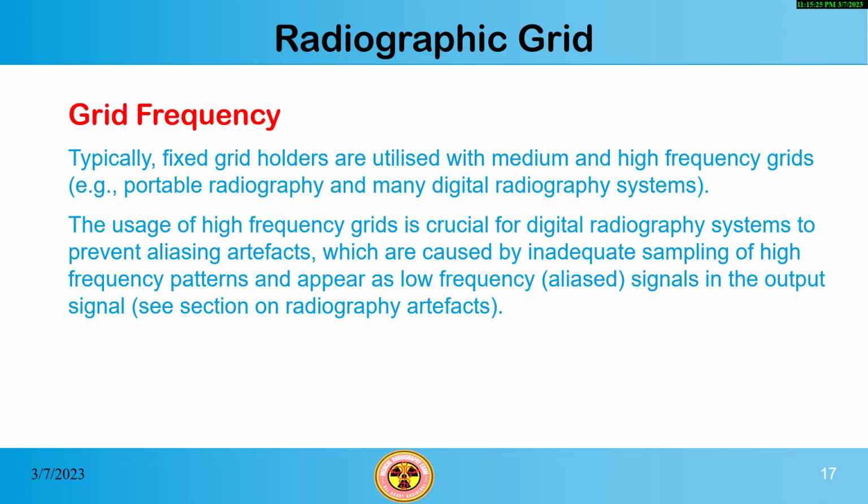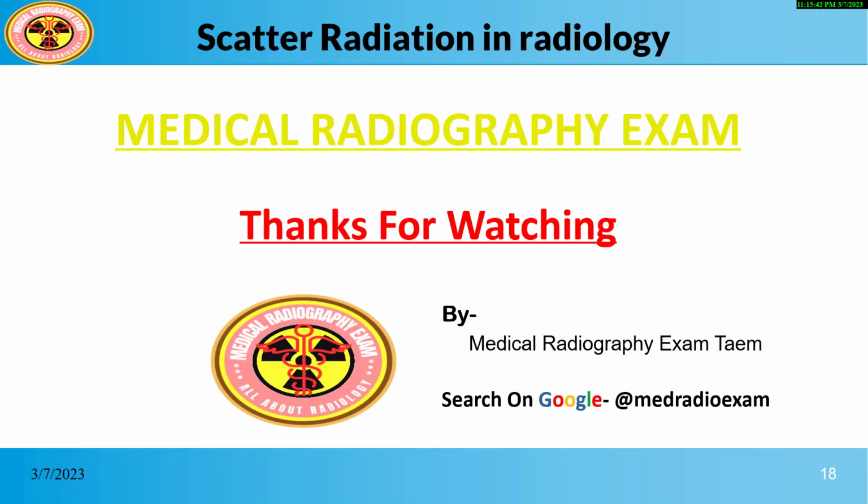The usage of high-frequency grids is crucial for digital radiography systems to prevent aliasing artifacts, which are caused by inadequate sampling of high-frequency patterns and appear as low-frequency, aliased signals in the output signal.